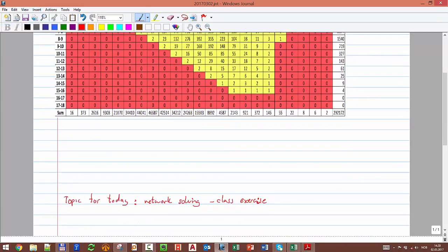I think you have to correct me. It's here, I think it's Tp, right? Peak period, and then you have significant wave height, yeah, and you have a bunch of points. And then I told you you have to also plot the 100-year wave line, between the interval between 5 and 20, I think 25, 20, okay. So that you know already how to make. I think that was relatively clear.